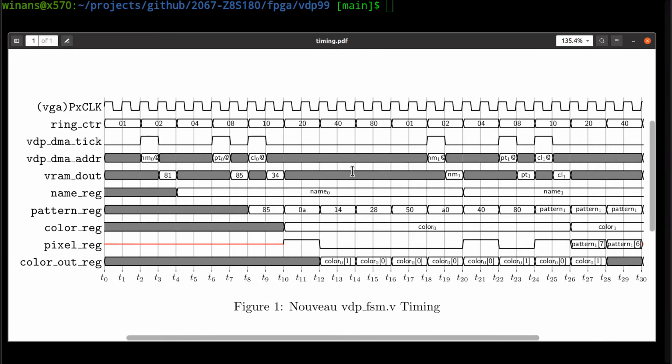The reason we care about that here is that we want to make sure these unused portions, when we're not doing these DMA ticks, happen often enough so that if the CPU is reading from the VRAM as fast as it can, there are always a couple of these times, which you can see there's a lot of in here, and most specifically that we don't hog access to the VRAM read data bus too long.